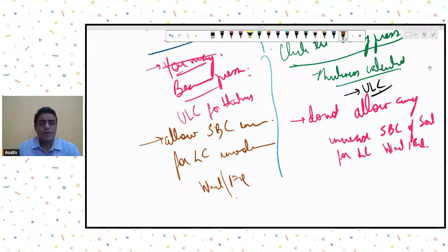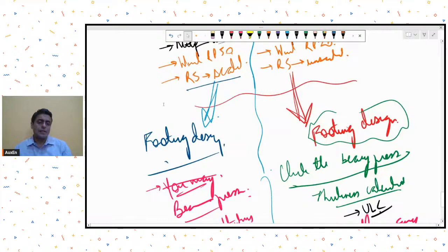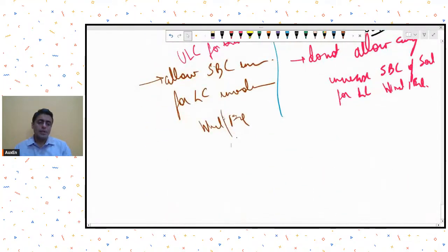So if you are using the strength model and taking it for footing design, because you are using 50 years return period and scaled base shear, I guess you may permit increase of your bearing pressure beyond the SBC value for load combinations involving wind and EQ. Okay, so this is what I just wanted to say.